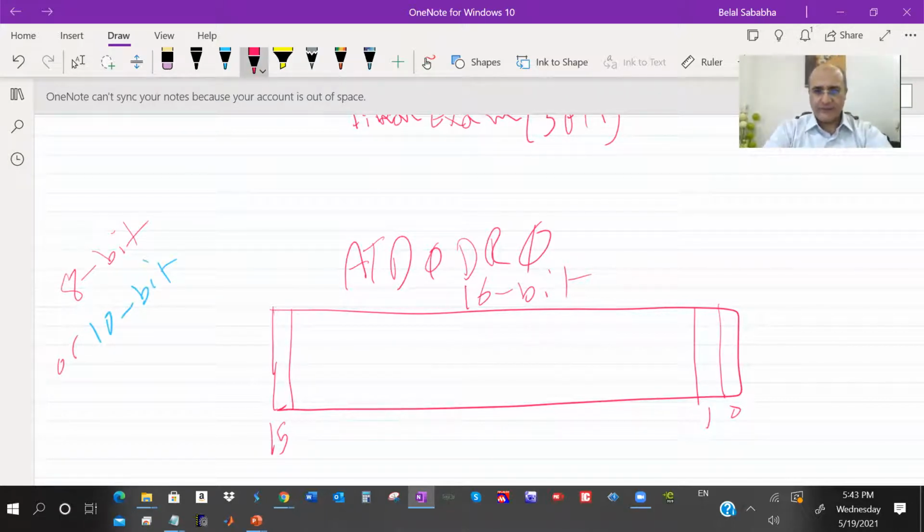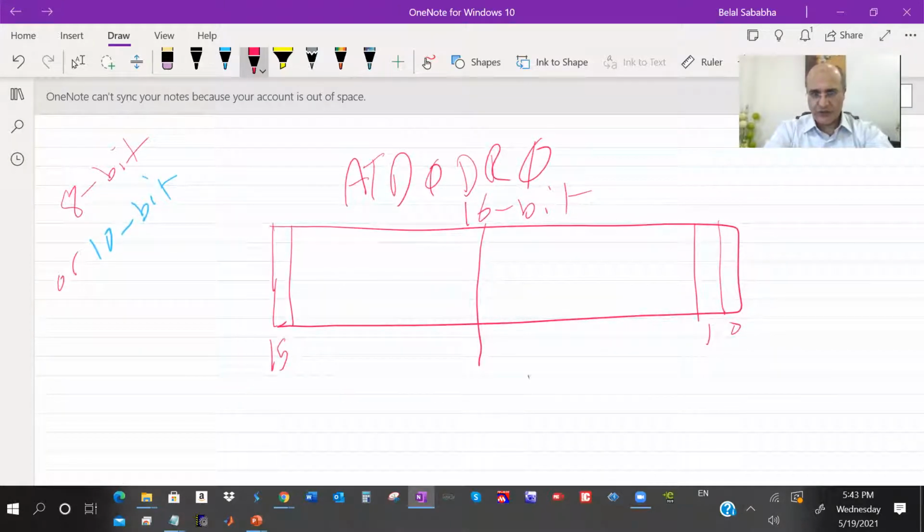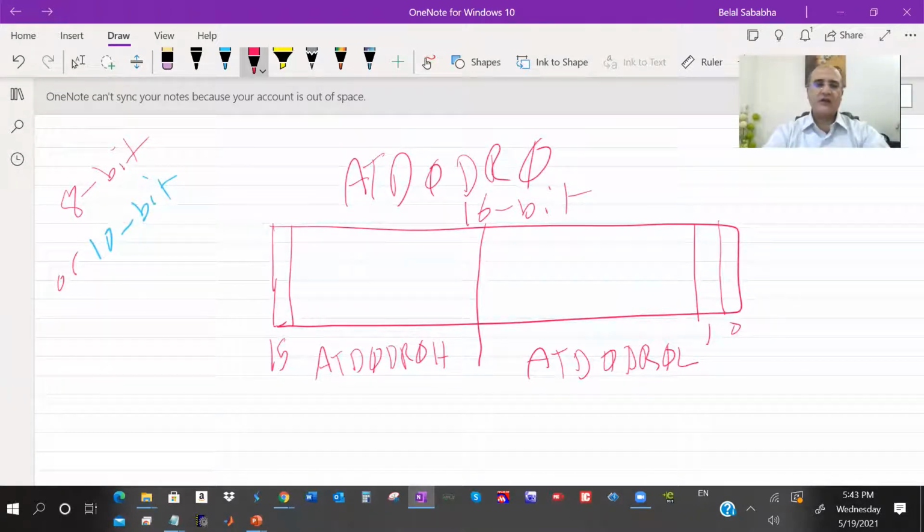If it's 8-bit, the 16-bit register is split: this part is called ATD0 data register 0 low, and this is called ATD0 data register 0 high. Same for data register 1 and 2 and so on. Okay, the 8-bit, if they're right justified, for example I read 1 0 1 0 1 0 1 0. They'll be stored like this here, right justified.